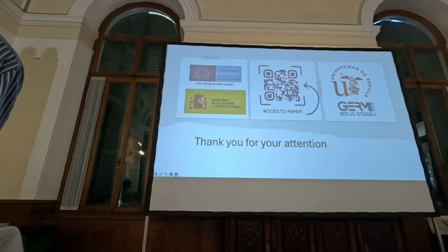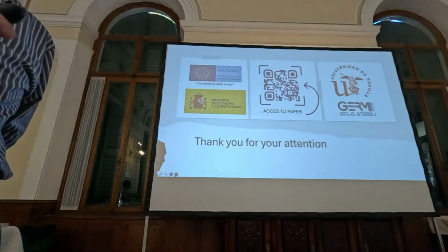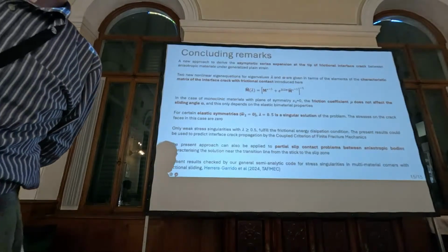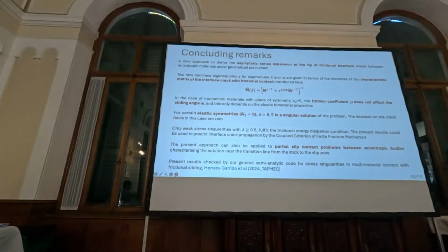Can you please make it more clear, if we consider shear loading of the crack, because you need contact between the faces. The question is whether in arbitrary loading we will have this condition, or even if we consider shear, there can be openings.